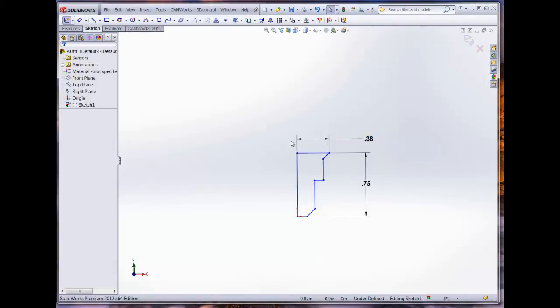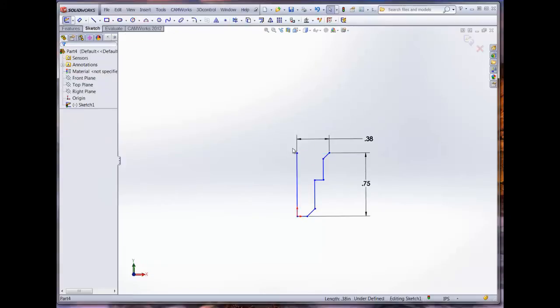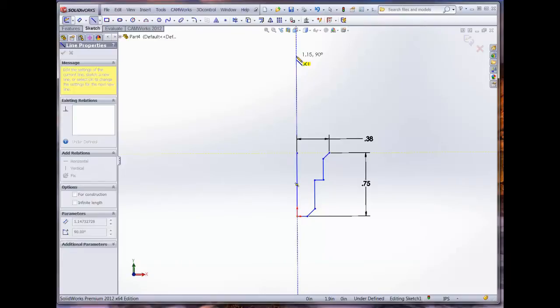Now that the cutting portion of the tool has been defined in the sketch, we can build an additional modification into the sketch, which includes defining the tool shoulder length. This modification allows for the overall length to be dimensioned, which we will define as a 2.5 inch long segment. This is another key value used in the CAMWorks definition dialog in the technology database.